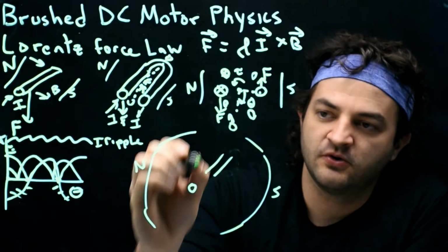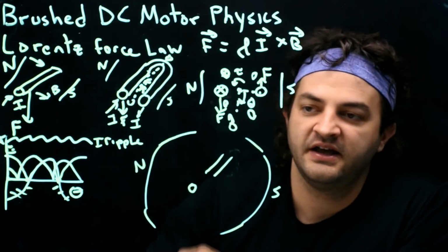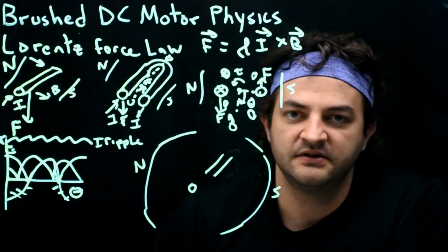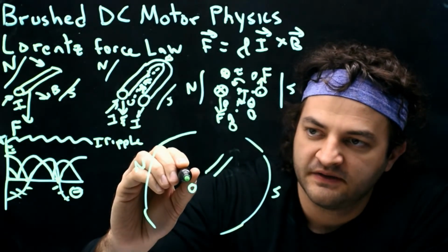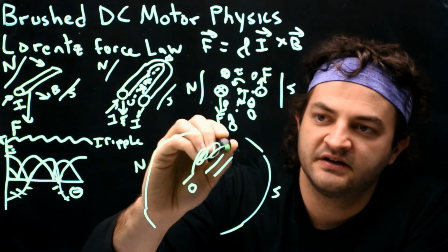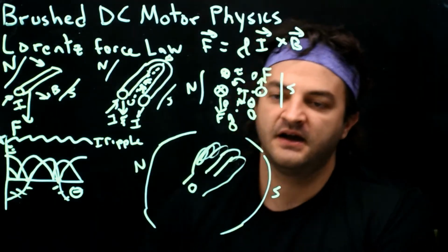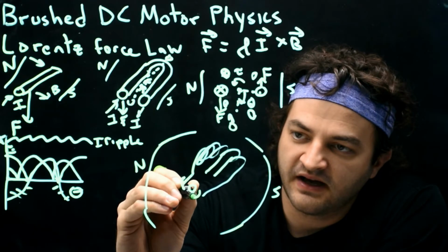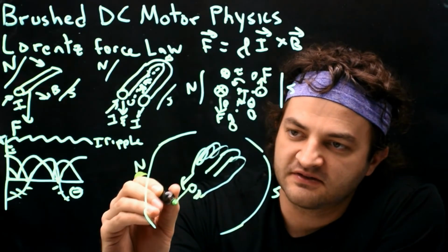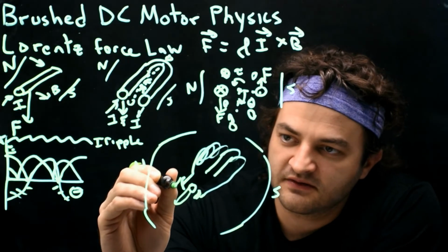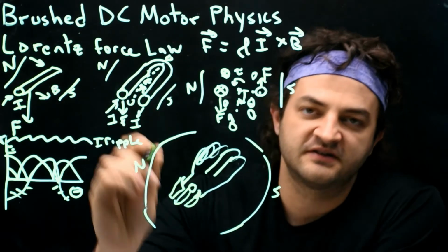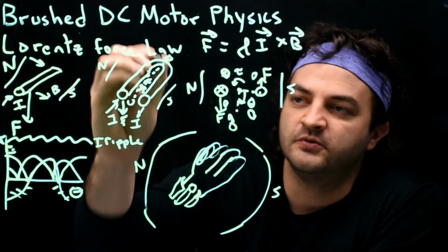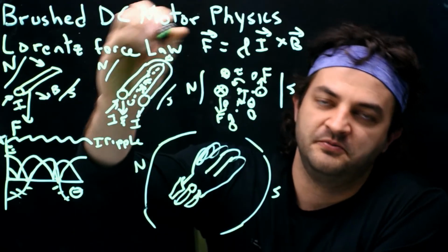So now what we need is our coils to be inside of this shell, filling it as much as possible so that we're getting as many in and out current lines as we can through the magnetic field. So we've got a wire that starts on one end, and then it does a lot of loops and eventually pops back out. That wire is going to be hooked up to a piece of conductive metal that's on the side of the shaft. So the shaft is coming out of the motor like this, and it's got a long kind of strip of conductive metal glued to the sides so that as the motor rotates, this piece of metal rotates. And that would be one of these loops, except instead of going in and out of the board, it would go in and loop and loop and loop and loop and then come back out again.